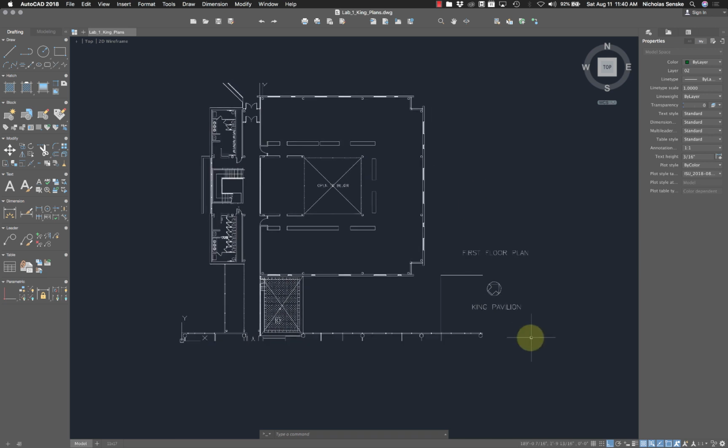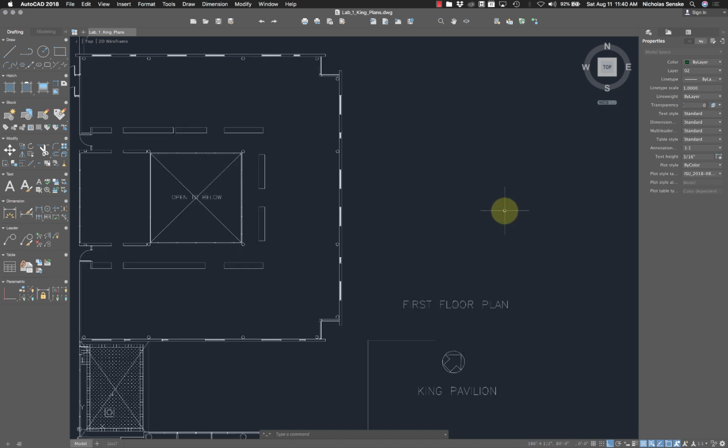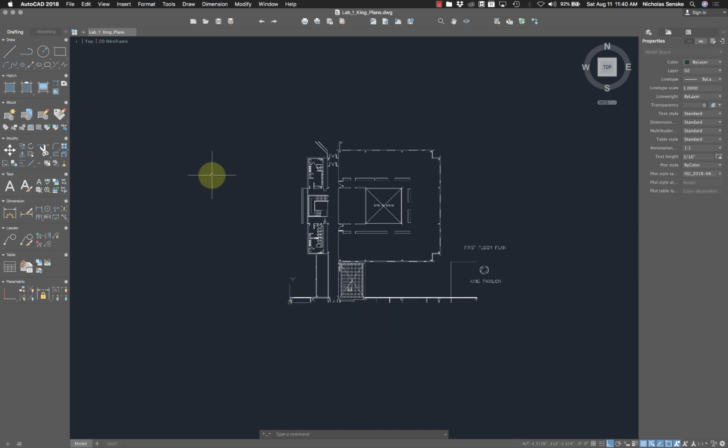Typically, when you do a site plan, you'll actually show true north, but when you're doing a building plan, it might help to align with something like a street or some other kind of datum, and that's what we've got going on here. So that's why that north arrow is facing an odd direction, but it is mostly north. So we do get a sense of where light might be coming in, where the western sun might be, that sort of thing.